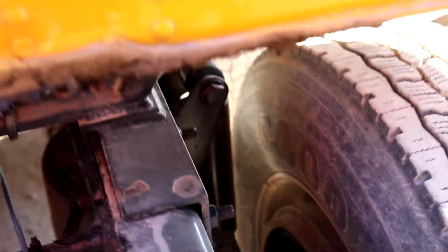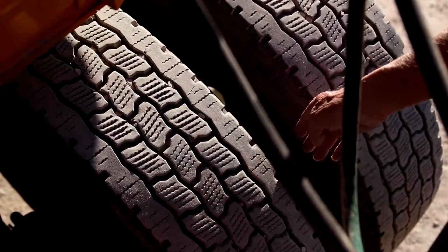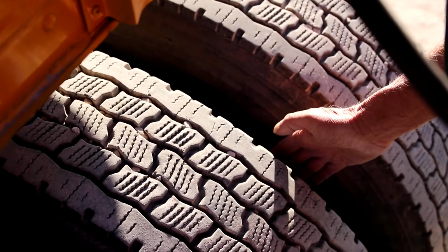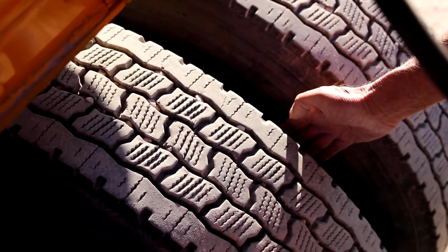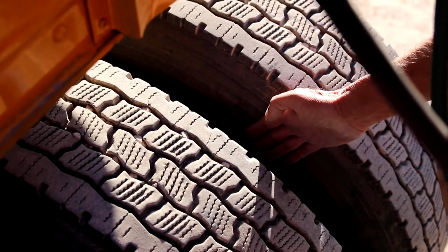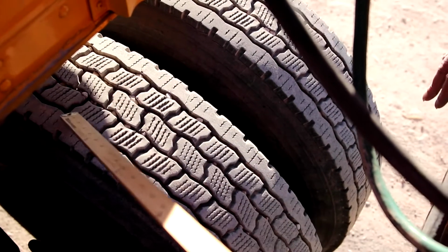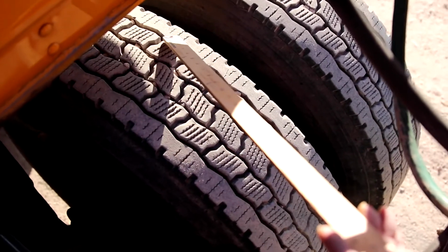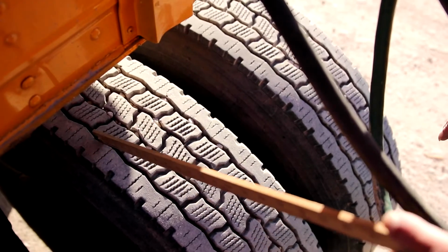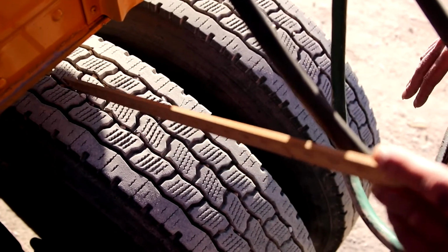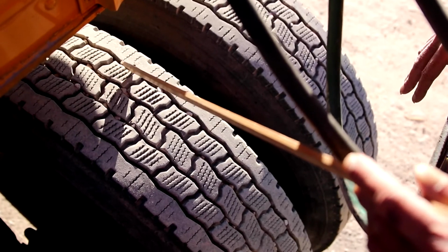Then you have dual tires here, so you're going to have to check both tires. My inner and outer sidewalls on my inner tire, no abrasion, bulges, and cuts, which would cause a blowout. They're mounted securely to the rim. My tread depth on this tire is wearing evenly. On these tires, you must have at least 2/32 of an inch of tread depth in each major groove.